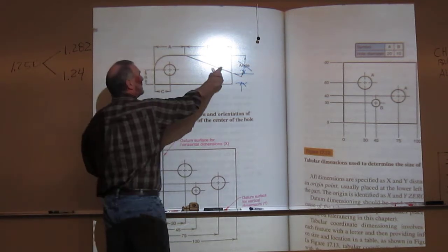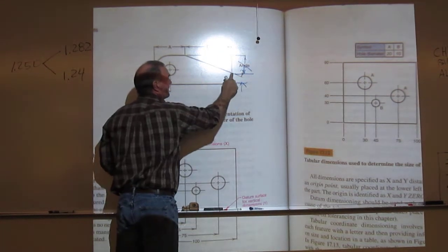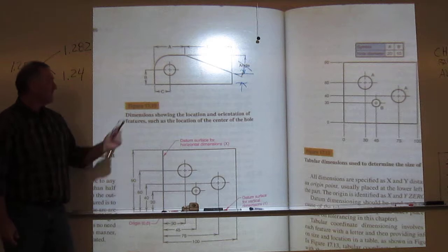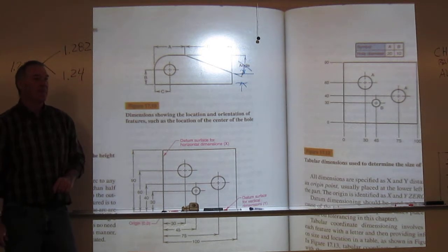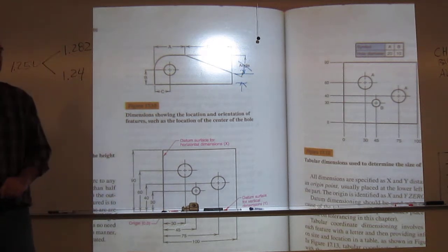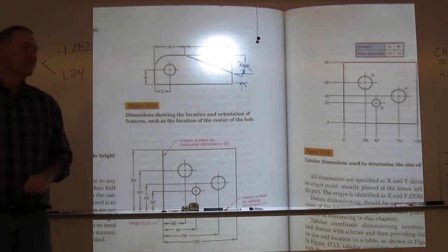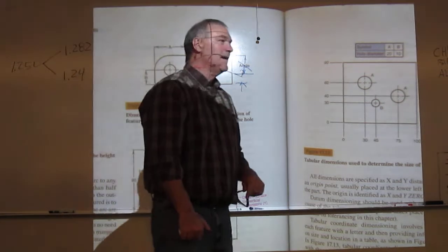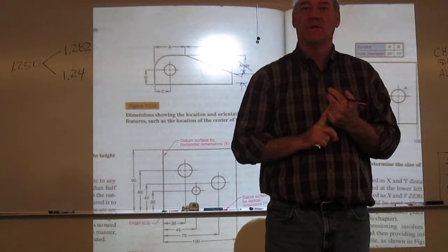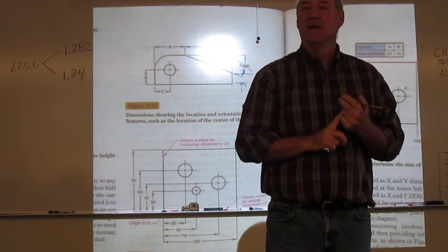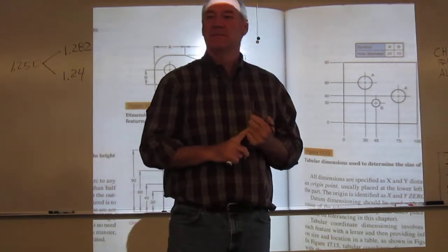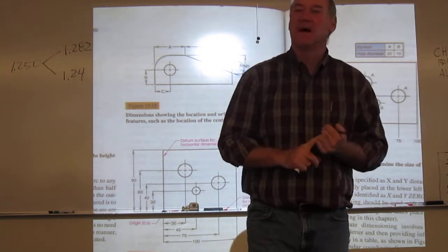So can I still construct this given this distance here and this distance here? Yeah, I'm given two lengths of the triangle. In essence, we can make a right triangle out of that. Why do we like linear measurements more than angled measurements? More accurate? Much more accurate. That's exactly why. More accurate to measure, more accurate to construct. Angles are tough to hit consistently. And if you have machines that work on angles, you're calibrating them all the time because they get off. So we want the linear stuff if possible.